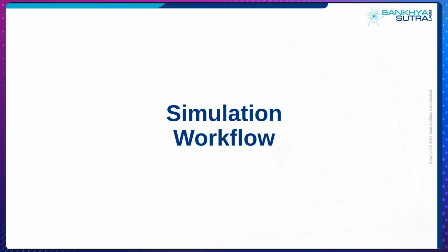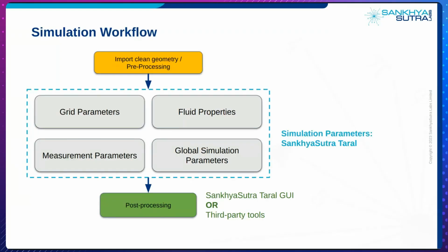Okay, so that was just a brief background of automotive flows and the motivation for using CFD in the workflow of automotive design. So I'll just give you a brief overview of the kind of parameters that need to be set for running a simulation using SankhyaSutra Taral. The first step, of course, is to import a clean geometry. That is essentially the pre-processing step. Then you set your parameters, which are user-defined parameters. There are 4 categories of parameters that have to be set.